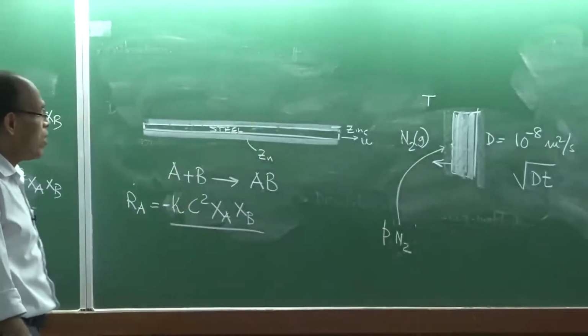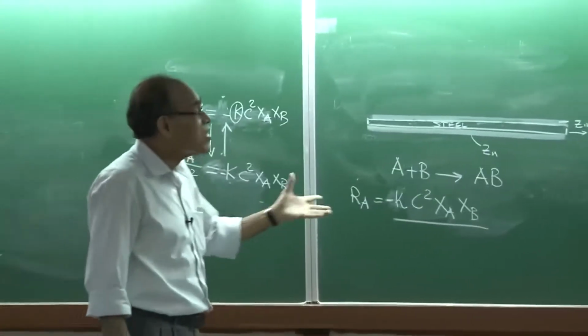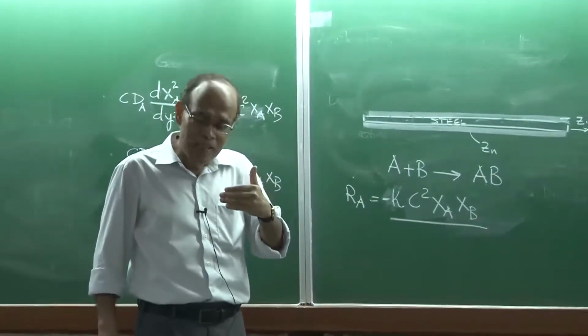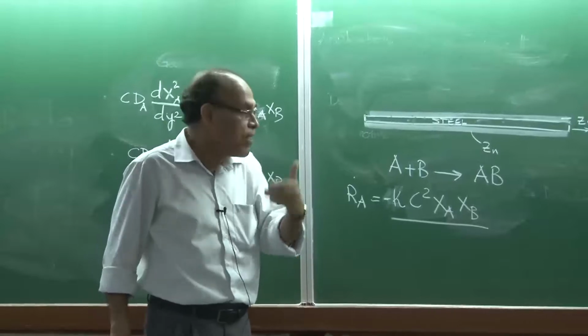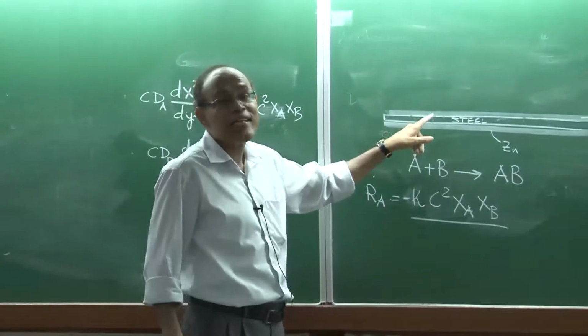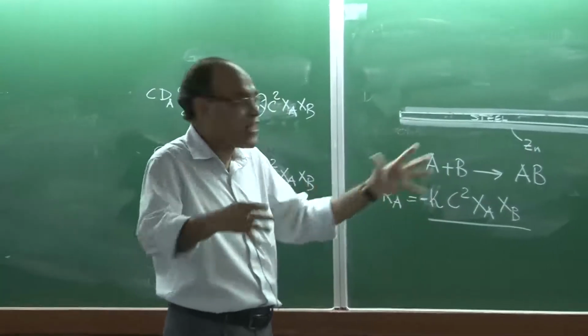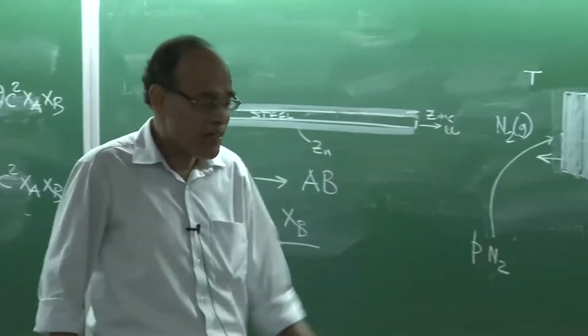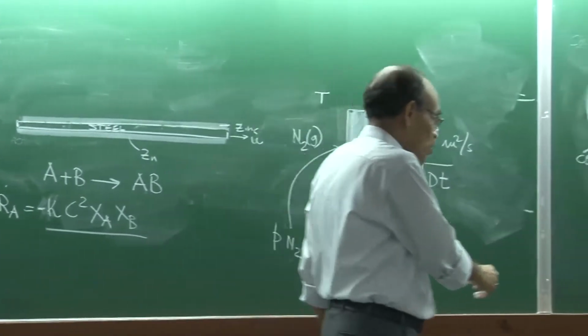This may be the case in the context of galvanization. And galvanization is not purely a diffusion problem. As I said, it consists of some part fluid flow, some part solidification, and the third and last part is the diffusion. All three, so it's a multi-physics problem, more complex than actually the carburization and the nitridation problem. So we'll continue with this.